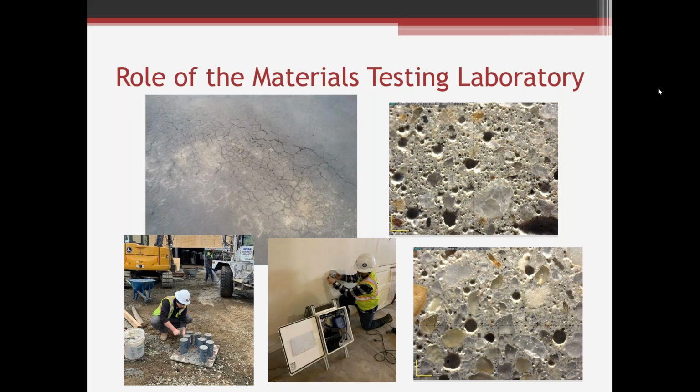That middle picture there on the bottom row, we're setting up a seismograph to monitor some vibrations during demolition in another area of the building. And that seismograph is fully automated. It records 24/7, and when values get above a certain level, emails start going off and texts start flying around. So there's less chance for harm to the structure.